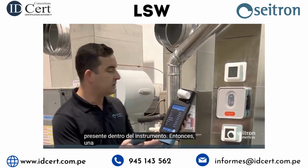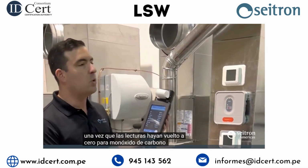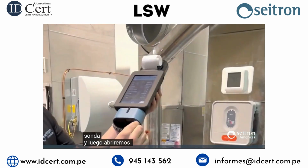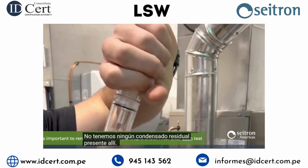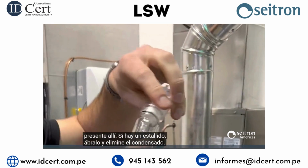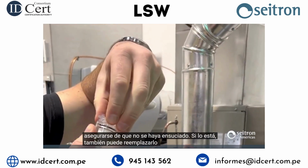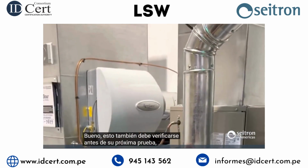Okay? So then once the readings have gone back to 0 for carbon monoxide and 20.9 for oxygen, you're going to disconnect the probe, and then we're going to open up the water trap and just make sure that we don't have any residual condensate that's present in there. If there is, pop this open and dump out any condensate. You can also check the filter to make sure it hasn't become dirty. If it has, you can also replace that at this point as well. This should also be checked before your next test.